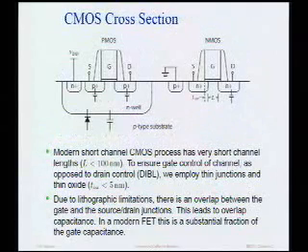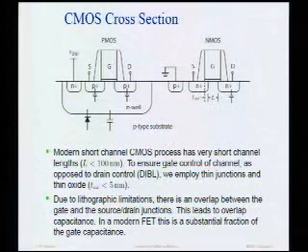Okay, so let's take a brief look at technology. Let's take a cross-section of our devices. Let's start out with our CMOS devices. Now, as you guys have learned in 105 and probably 130 and other courses, the way we build modern CMOS devices is we basically start out with a p-type substrate, and directly in the substrate we can build an NMOS device. NMOS device is basically 2 N+ junctions and a gate. A gate is insulated, of course, from the substrate with a thin oxide. And by applying a gate voltage, I can form an inversion layer here, which is a channel for current to flow from, let's say, the source to the drain.